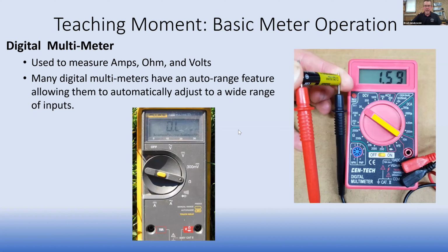All right. Things also then, if you haven't done this kind of work with your students in the past, just like I have in this photo here, you can have them work with some batteries. When you have a battery tester, you're finding out if it's actually delivering 1.5 volts, or the number of volts that it's supposed to. So you could set this at 20 volts DC, put a lead on each of the ends of a battery, and do that.